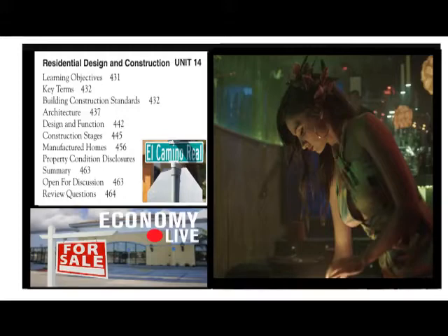Building codes are enforced by the appropriate municipal or county governing authority. A building permit must be obtained before construction is allowed to begin. Application for a permit is made to the local building official, who also is supplied with plot plan and building plans and specifications for the proposed structure. Problem areas are pointed out and can be revised. The permit is issued only when the application is finally approved.